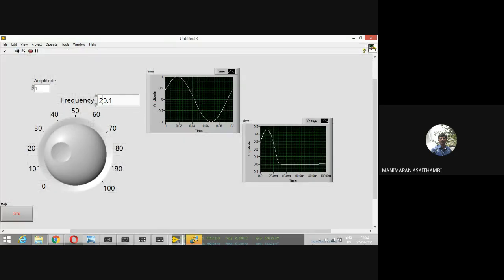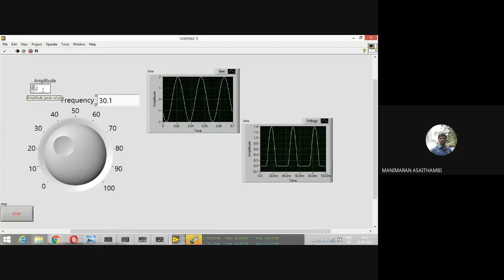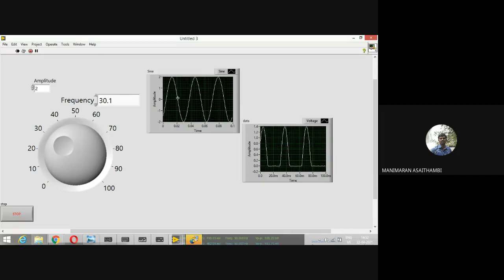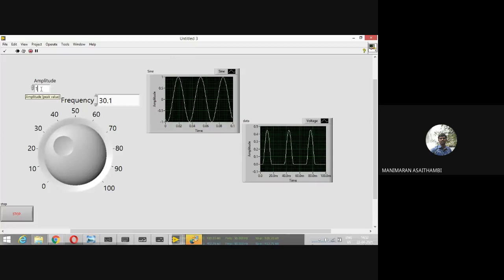So now when we go for higher frequencies, we could see them. If you see over there, whenever it is generating one, I have only the positive peak there. We can add more higher samples, so we could see that. Out of 2 volt, I'm getting only 1.4. So 0.7 is being cut off there. 1.3, nearly 2 volt, 0 to 1.3 there. When I say 1, it is only nearly 0.4 or somewhere there. 0.65 near to it, it got cut off.